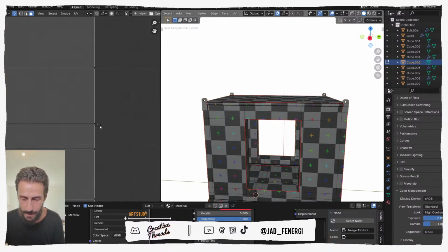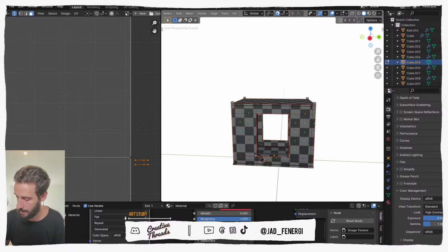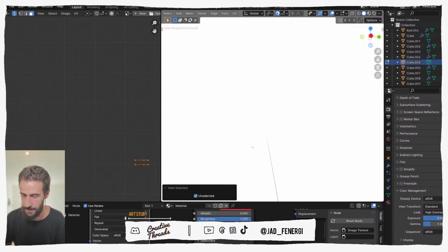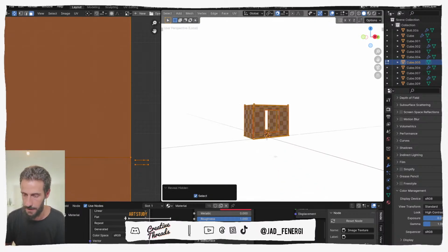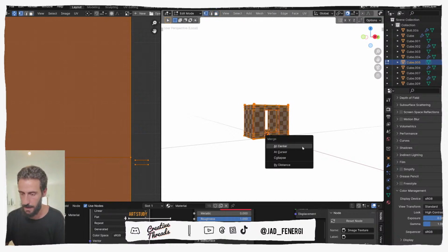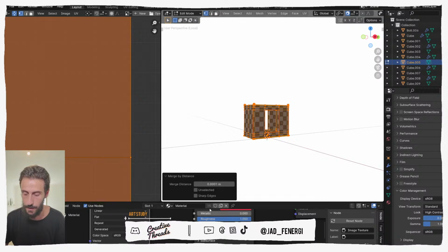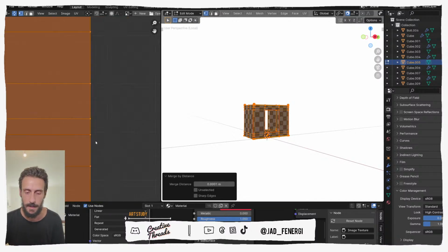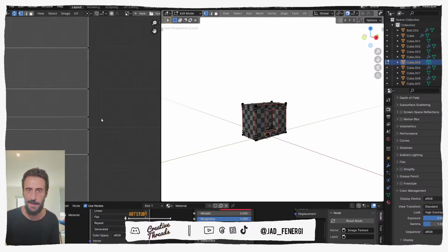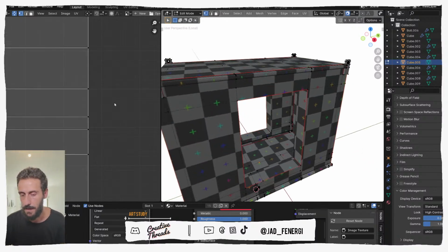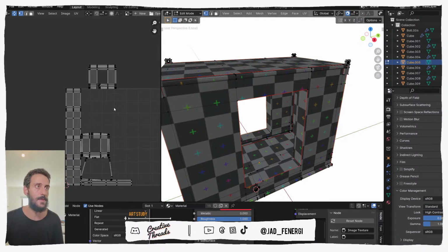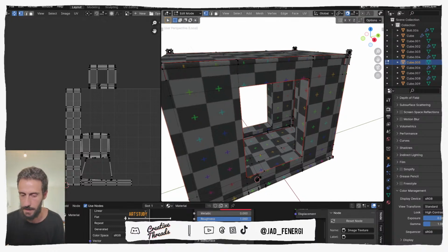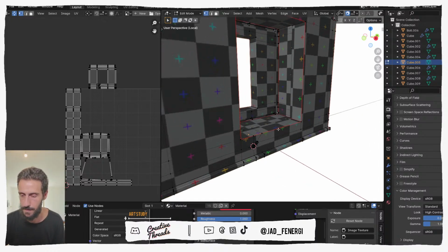Where is this? So these are these guys. If you press Shift H, so probably something in my model. I'm going to press Alt H to bring everything back. Press A on the vertices, then M, merge by distance. I'm merging. So I merged these 4 vertices, and they disappeared. I think they were faces that needed merging. So the nice thing about Blender is that you can merge and you can create edges even if you unwrap the geometry, and it still works. That's usually not the case with some other tools.